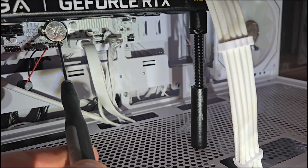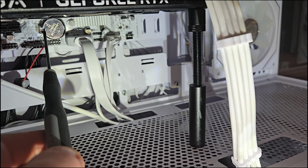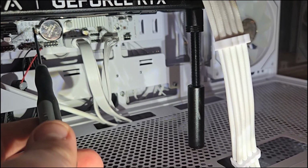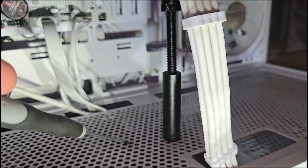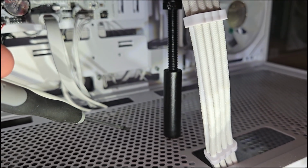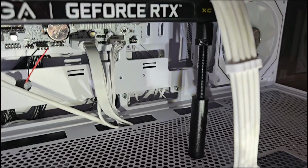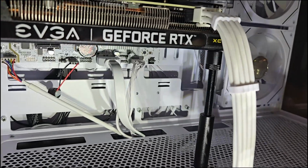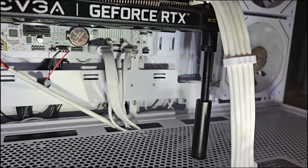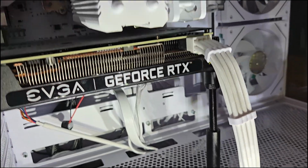I'm not going to do that because my BIOS and everything is working, but you're going to have to get this out lightly with the screwdriver, and then put it down here or so. Hold the screwdriver to it for like 10 seconds, then wait a few minutes and plug it back in. 5 to 10 minutes or so. And that will restore your BIOS. Sometimes it is hidden behind your GPU, so make sure it's not.